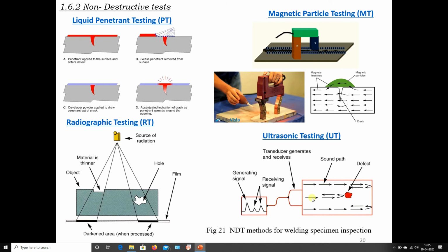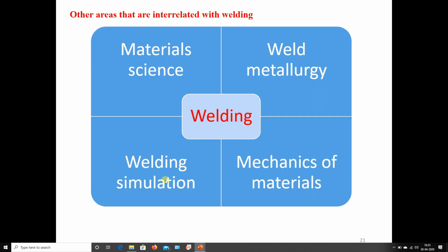Here is the probe, we have to use some lubrication over the surface so that we can protect the probe from damage. And in radiography we have a radioactive element, and we are afraid to handle it, so we should take care. We have some badges, some indicators, we should hold in our pocket so that it will tell how much radiation you have absorbed. Okay, we should take care. So both things will be very helpful for you.